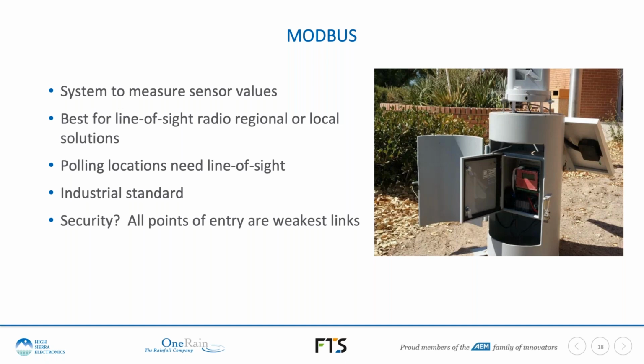MODBUS is not, from a radio protocol point of view, a very secure thing. With a MODBUS network, any of the entry points are its weakest links, and when you use radio protocol, basically every site is an entry point, and so is the central polling master that's pulling the data in.